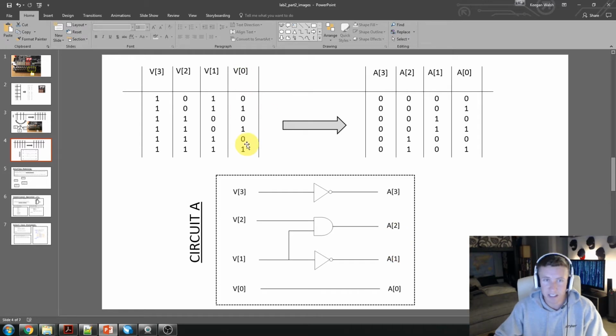Now if we look at the least significant bit column, those are the same, so we don't have to do anything to it. Fantastic. The second one, we have to say, okay, how do we only get a 1 here and a 1 here? If you think about it, I have AND gates, OR gates, NOT gates. We can't just use a NOT gate here. But if you AND together the second and the first bit columns, you'll get this result, right?